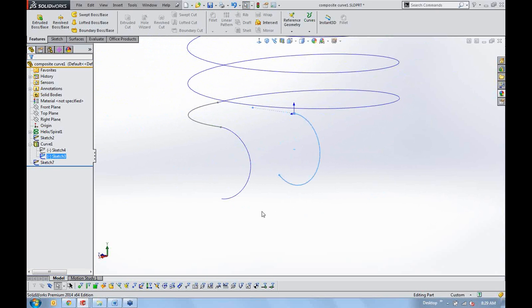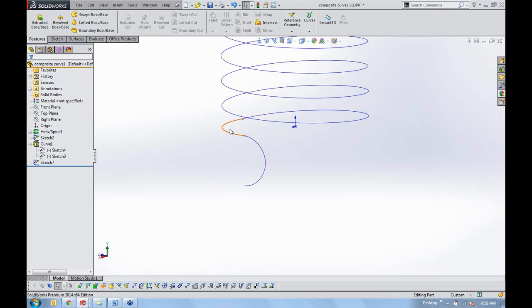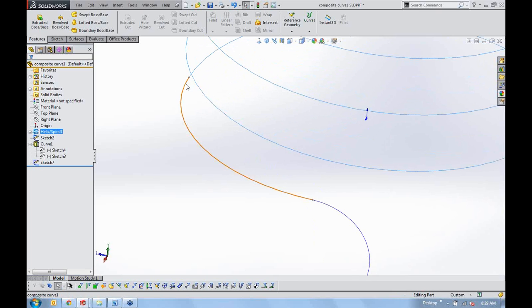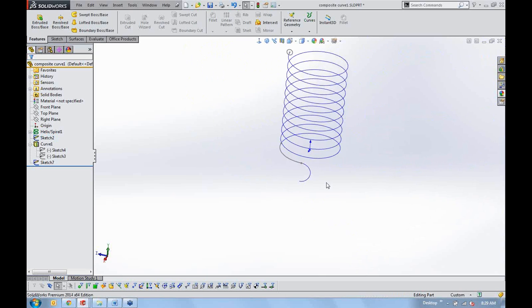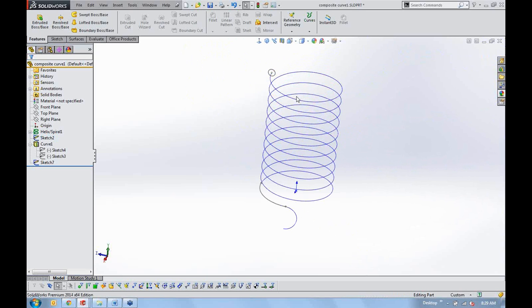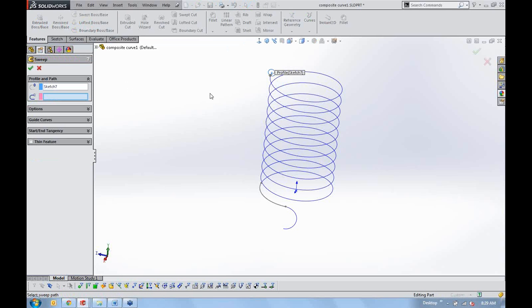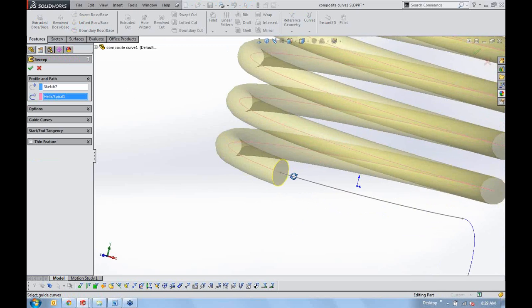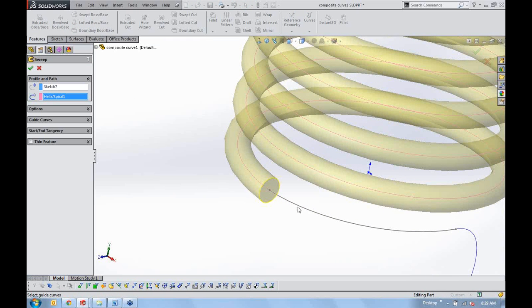Again, if you wanted that geometry. And then here, the helix actually ends over here. And I just created a 2D sketch, you can see sketch 2 here, of an arc with the same radius as my helix. Well, if I wanted to sweep my wire now for my spring, I would very easily go to Swept Boss, click that, and click my path. Except it stops at the end of my helix. Broken, right? Because this is a separate entity.